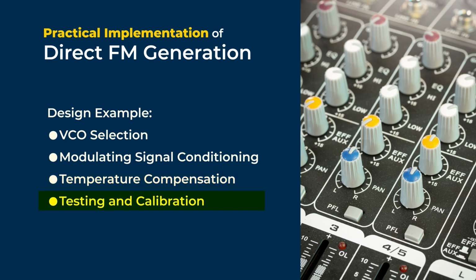Finally, testing and calibration. Test the system to verify the linearity and stability of the FM signal. Calibrate the system if necessary to correct any non-linearities or drift in the output frequency. So, this is all about the designing of direct FM generation.